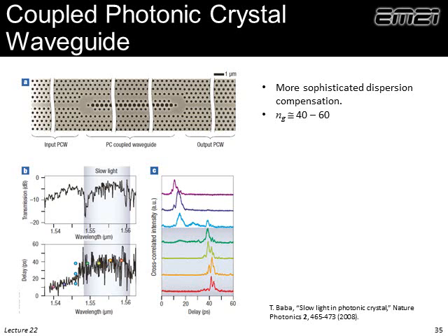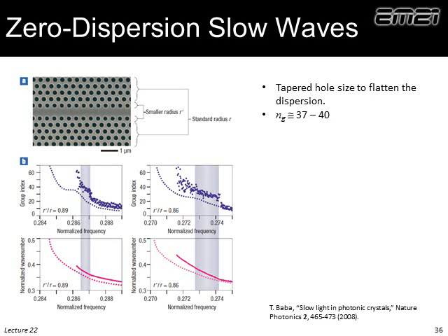So we can introduce a lot of delay and dispersion by introducing more interaction of the wave with whatever it's in. Here's a device that claims zero dispersion for slow waves. And what you notice is that we're chirping the hole size here. We have our waveguide surrounded by a photonic crystal. And it's maybe hard to see, but notice that the hole size increases as we go outward.